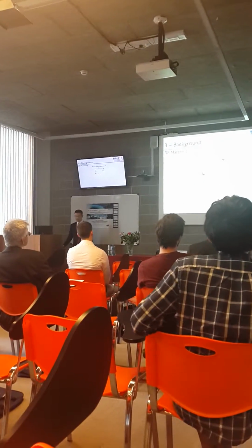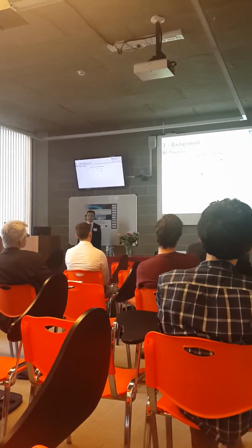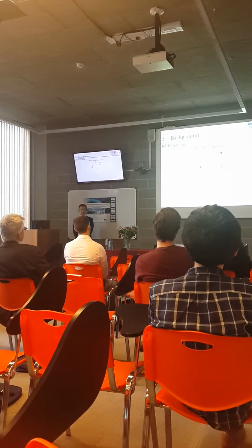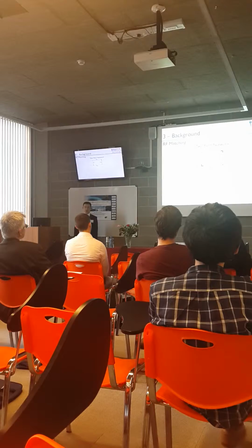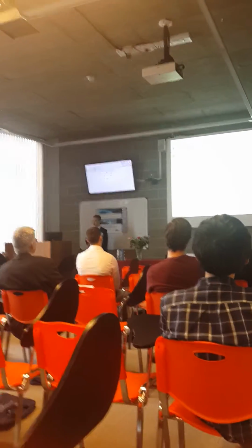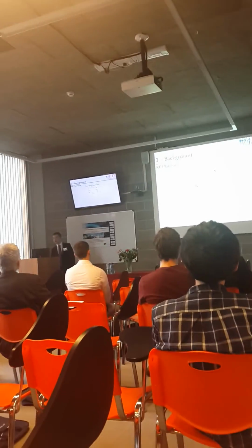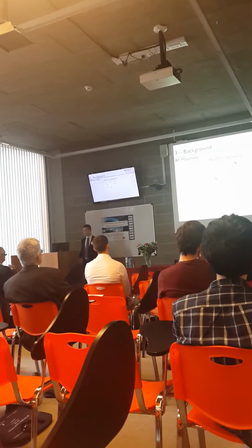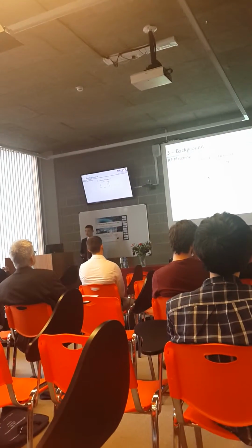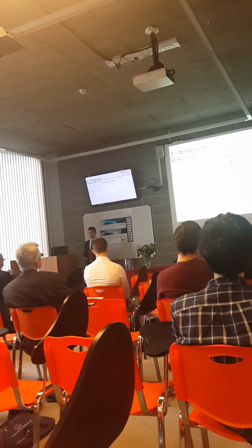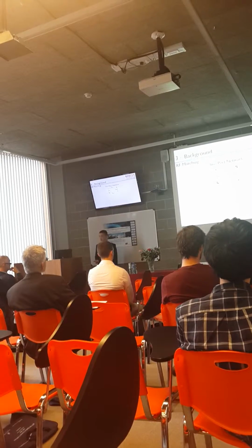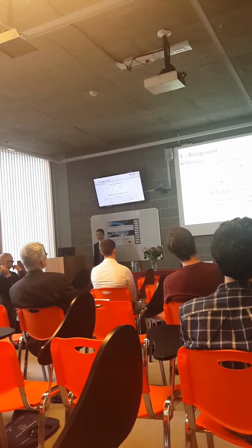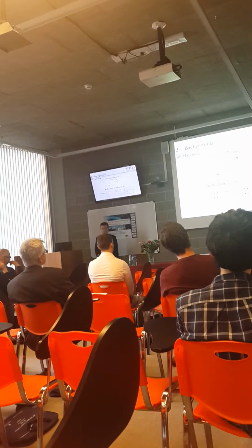In RF circuits, normally a 2-port network is used to describe these components. Particularly, S parameters are used to describe the low noise amplifier. For example, S11 is used to describe the input reflection coefficient, and S22 is the output reflection coefficient. As you could consider, the lower the value, the better. So the receiver blocks become the 2-port network shown here.